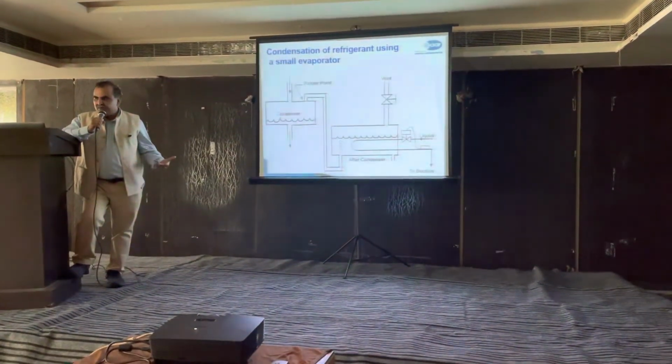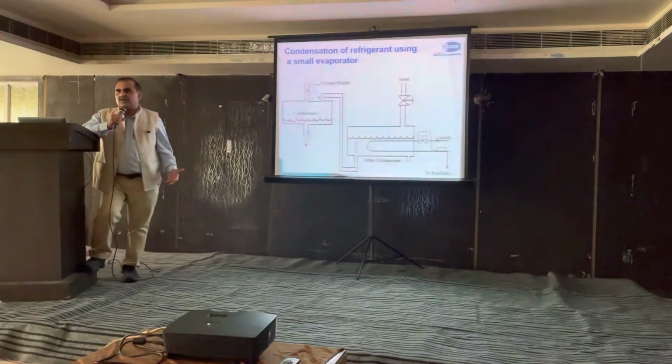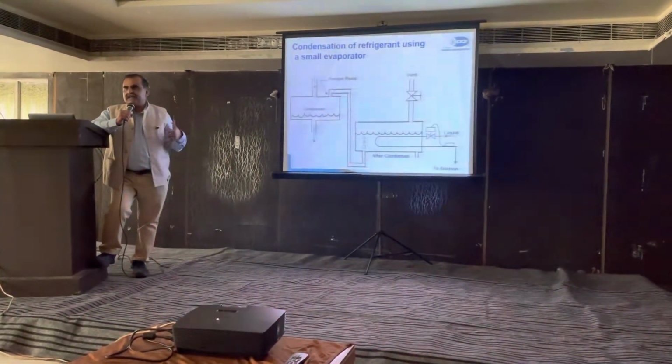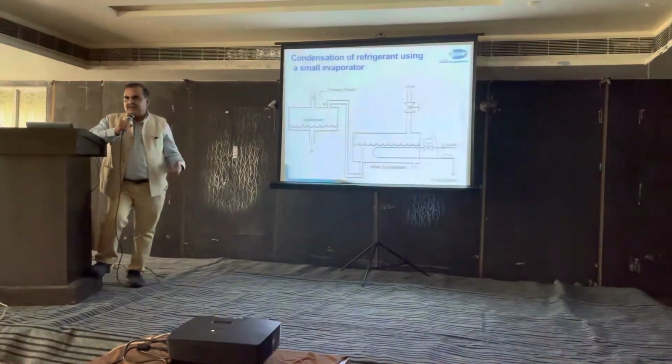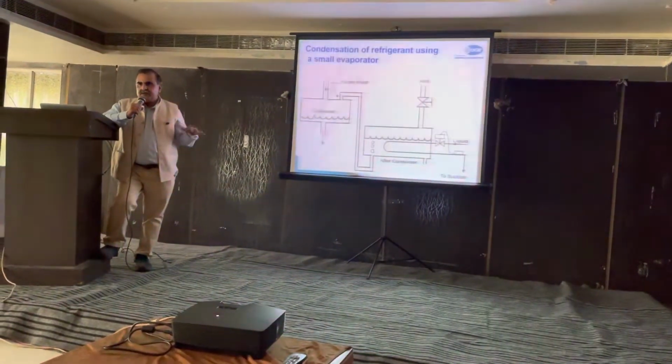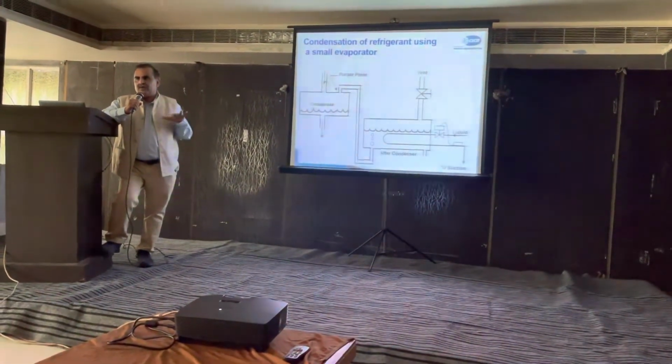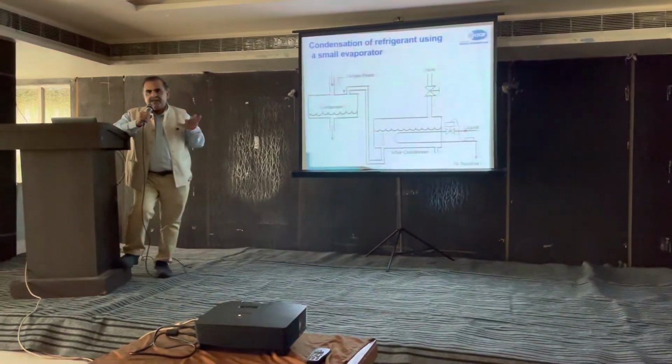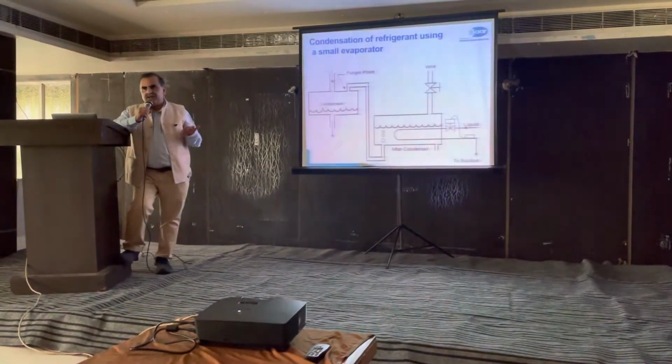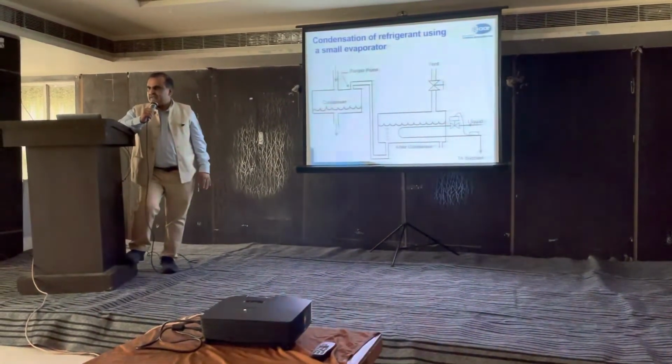This purger does not require extra power or an extra compressor to run, and it runs as long as the plant is running. There is no need for installing it above the condenser or above the receiver. It can be installed anywhere in the plant room, next to the receiver, next to the condenser, wherever space is available.